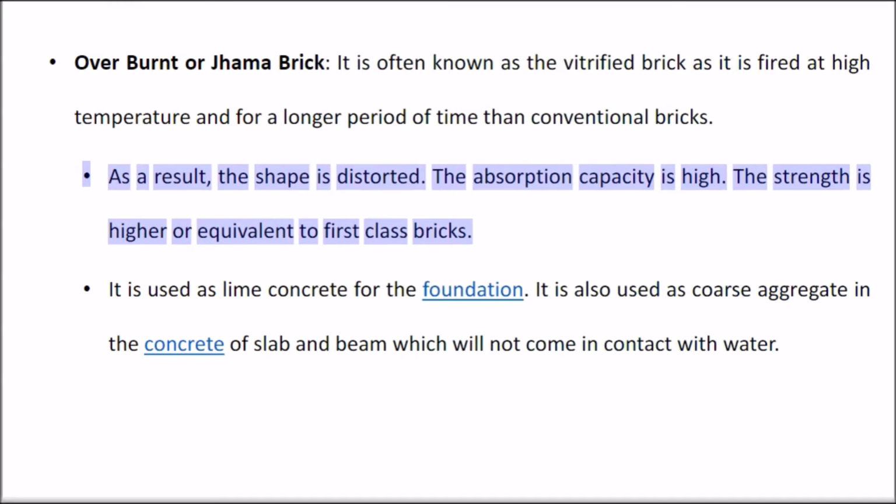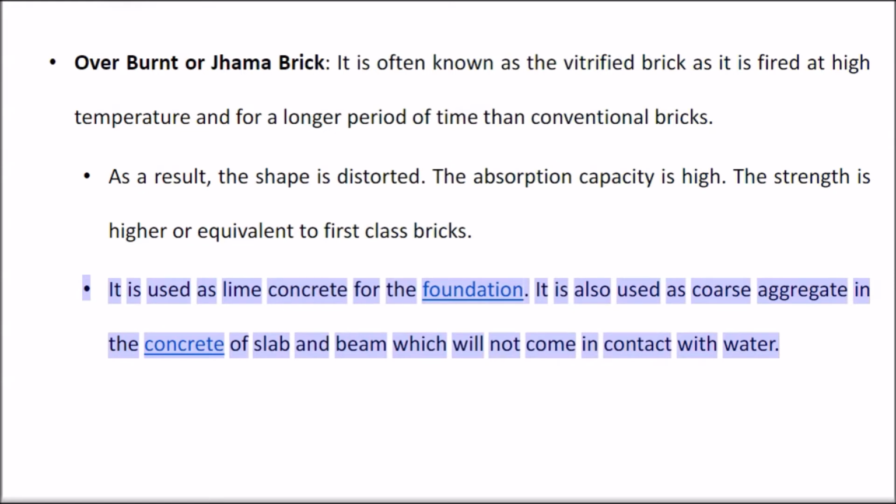The absorption capacity is high. The strength is higher than or equivalent to first-class bricks. It is used as lime concrete for the foundation. It is also used as coarse aggregate in the concrete of slab and beam, which will not come in contact with water.